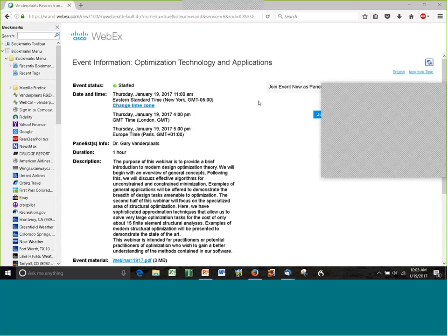Topology, if you imagine that first picture I have where you have supports and a load, and you'd like to know what structure to put there, you can begin by just putting a flat sheet between the two supports with the load and tell it that you want the stiffest structure you can get, but only use 20% of the material. Topology will cut out holes, if you will, in the structure and eliminate all the unnecessary parts, but leave you with the stiffest possible structure.